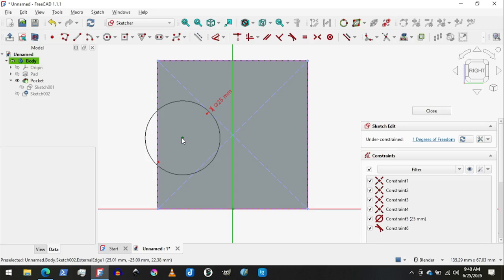Now, some tools like Onshape will save for you automatically, which is really nice. But I'm going to go ahead and save this, and I'm just going to call it part 08. So all the sides are the same, and I can go here using the measure tool and check my work. If I click this edge, I can see it's 50 millimeters, 50 millimeters, 50 millimeters. And if I check my drawing here, okay, there's one thing missing.